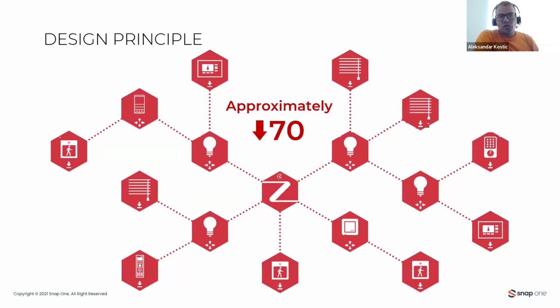So generally, it is not a good practice to use the director, which is most commonly in the rack, as a Zigbee access point. Typically, the Zigbee access point should be some controller which is located in a room relatively close to the lighting installation. That means relatively close to the lighting controllers. So we have good close interaction between the Zigbee access point and the Zigbee lighting controller.